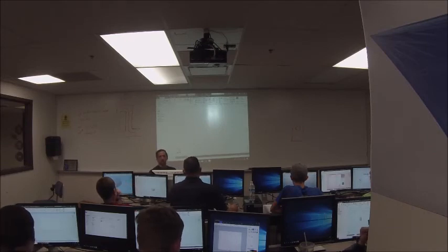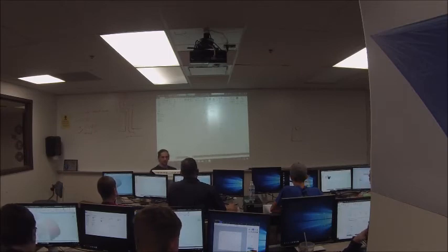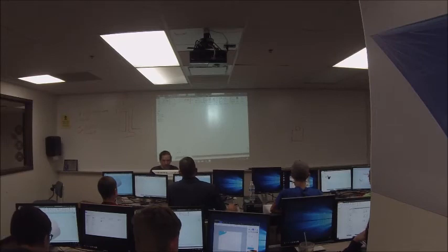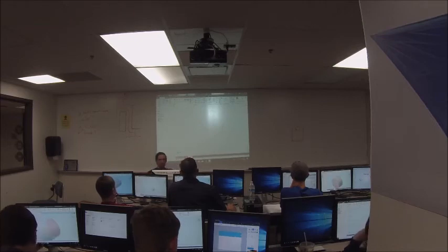How do you add a part and switch between them? You just go up here and click this button, and it'll bring up this window, and then you just double click on standard.ipt. And how do you get back to the other ones? They're down at the bottom, there are little tabs. So you can just click the tabs back and forth. If you fill up this bar, it'll just add a little scroll bar and keep going, so you can have 100 parts open if you want.